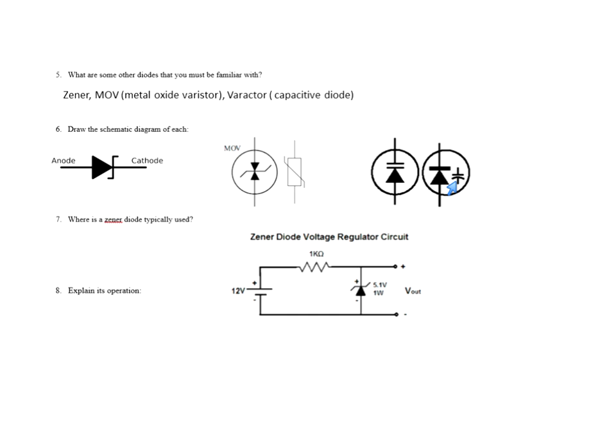Okay, now, where is a Zener typically used? A Zener is used for voltage regulation. Do you know what a regulator is? It holds the voltage steady. Over here is your typical Zener circuit. Hopefully you covered some Zener in your second quarter.